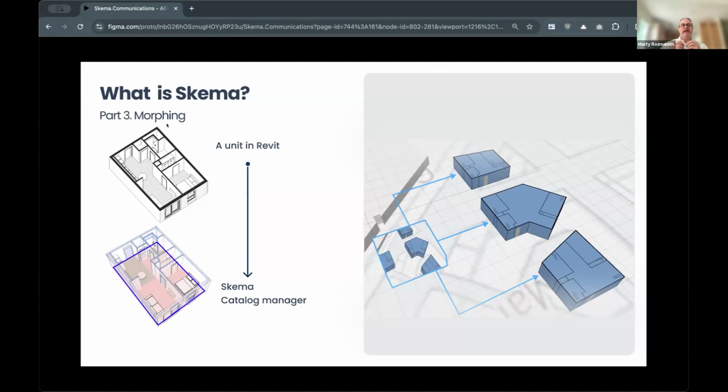And whatever extensions you made to the properties, whether type or instance properties, in those things in the model, you're going to see them when we put them back out into Revit, because we're storing a binary blob of that definition. And when we write it back out to a Revit file, it's going to have anything that you've put into that type definition or instance definition that we captured when we brought it into the assembly, stored in Schema. So that's another big thing that makes us different than some other solutions.